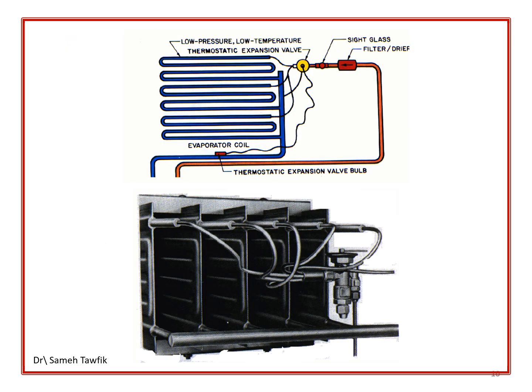The top image shows the internal structure of a thermostatic expansion valve, a key component that regulates the flow of refrigerant into the evaporator coil. The bottom image depicts a bank of these thermostatic expansion valves, likely installed in a larger refrigeration system. These valves work together to precisely control the refrigerant flow based on temperature, ensuring efficient and effective cooling. The images illustrate one of the operation control elements described in the previous slide, highlighting the critical role of the thermostatic expansion valve in the refrigeration cycle.